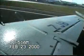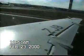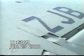Type 4 is an enhanced performance fluid with anti-icing effectiveness superior to type 2 and increased holdover time. Similarly, Type 2 is more efficient than Type 1 fluids. Type 2 and 4 fluids offer significant operational advantages in terms of holdover times.